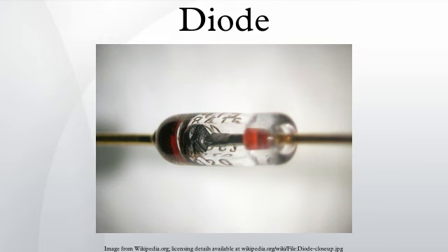A diode's I-V characteristic can be approximated by 4 regions of operation. At very large reverse bias, beyond the peak inverse voltage or PIV, a process called reverse breakdown occurs that causes a large increase in current that usually damages the device permanently. The avalanche diode is deliberately designed for use in the avalanche region. In the Zener diode, the concept of PIV is not applicable.